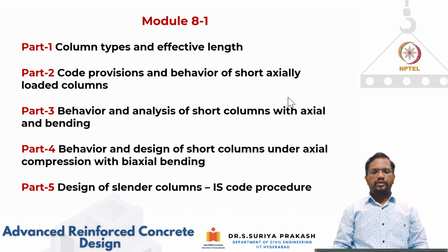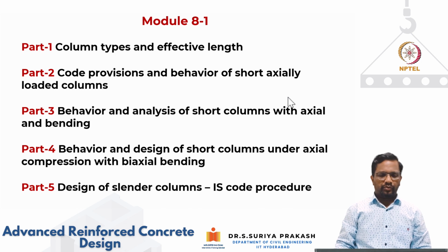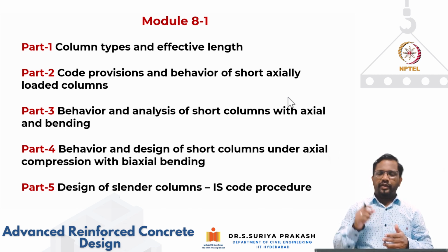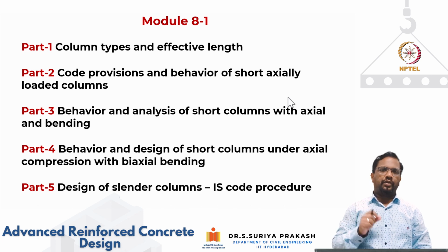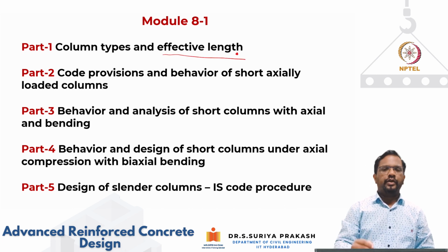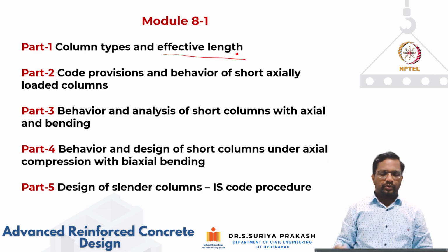In this part of this video, we are going to discuss how we classify the columns, and a very important classification of a column is whether to design the column as a slender column or a short column. So for that, we will be using effective length. So we will talk about that.